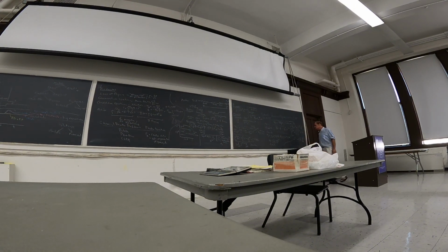Finally, I have CA of t equal to CA of 0 times e to the minus t over tau, plus CA in times 1 minus e to the minus t over tau. And we will analyze this next time. Here we have the solution, and it always works this way. We will start with that next time.